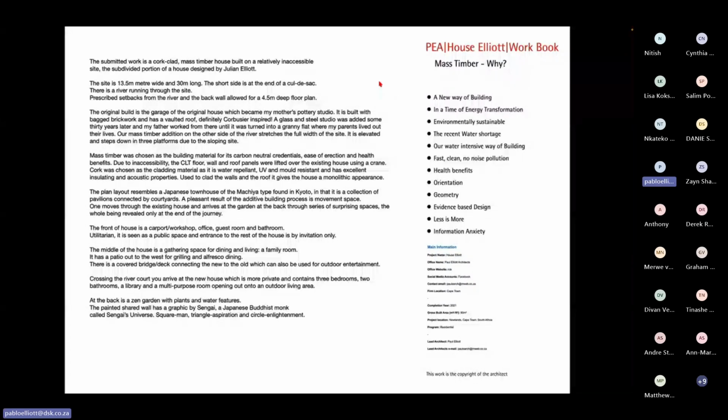It's called mass timber because it has to do with large pieces of timber that are either glulam beams or columns, or cross-laminated timber panels, which can be used for floors, walls, and roofs. So they're saying the 21st century will be the century of mass timber. Why? It's mostly applicable to Europe and Canada, heavily forested countries, because it's a sustainable way of building.